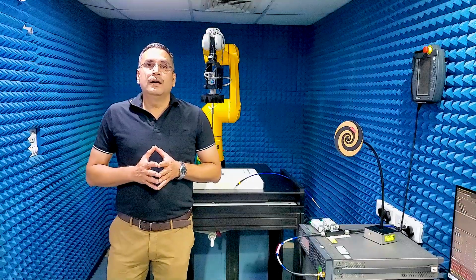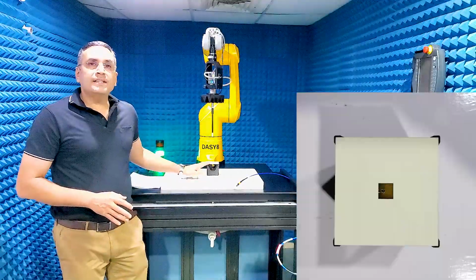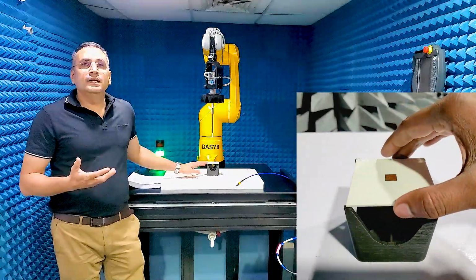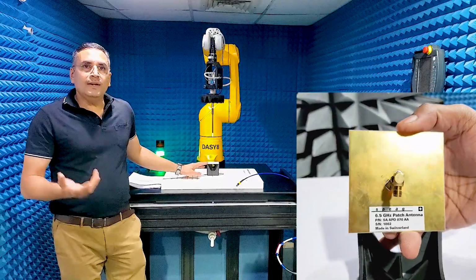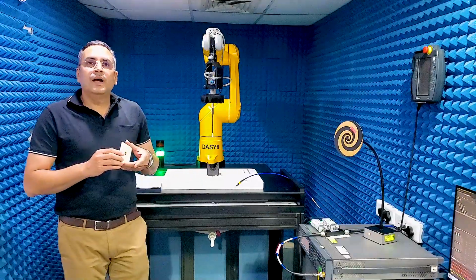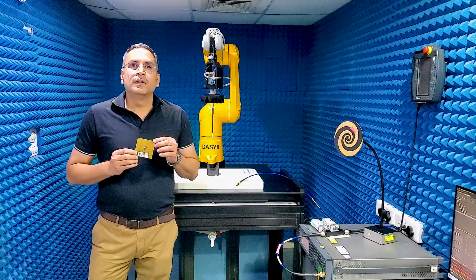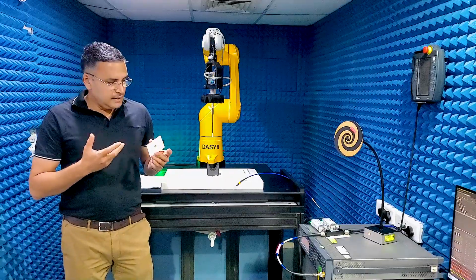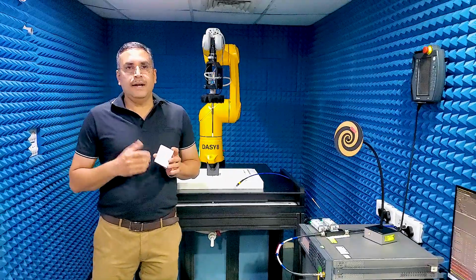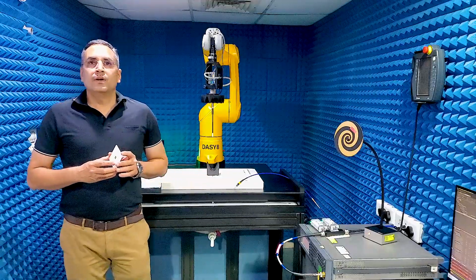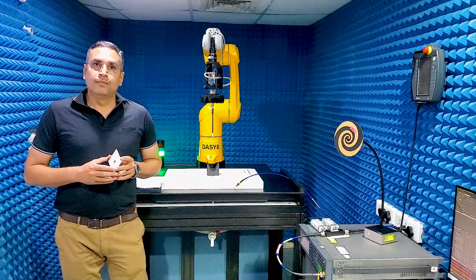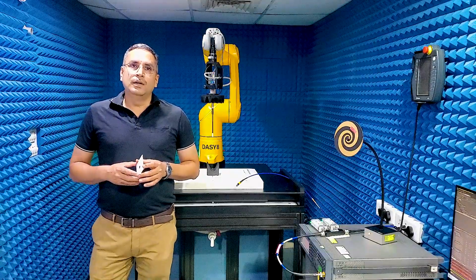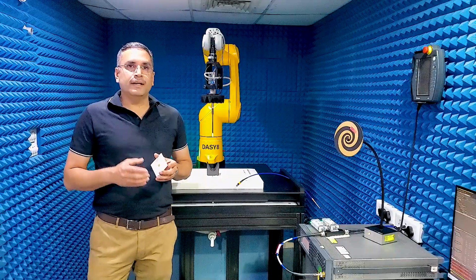However, today I will first test this patch antenna that SPIAC just released for system check for the Wi-Fi 6E bands. I will evaluate this patch antenna at 6.5 GHz with the latest beta version 3.2 of DASY8 millimeter wave module, and then with the APD feature of module SAR version 16.2. Afterwards, I will also check the multi-TX evaluation capability of the new software on specific phantoms.